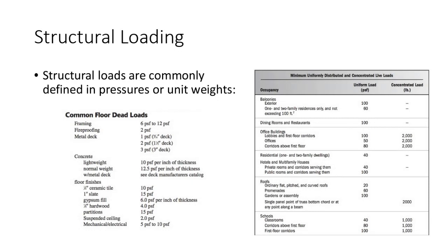So in a structural engineering context, the primary source of dead load is the structure itself. So if I'm talking about a building, I'm talking about the actual structure. We might be talking about the framing, the metal deck that forms up the slab. Let's talk about my office right here. This is a steel framed building, so there's the steel frame itself. The floor is a concrete slab, so there's so many inches of concrete. Concrete weighs, we typically assume, 150 pounds per cubic foot for normal weight concrete that's reinforced. So however many inches thick the slab is, there's a pressure load.